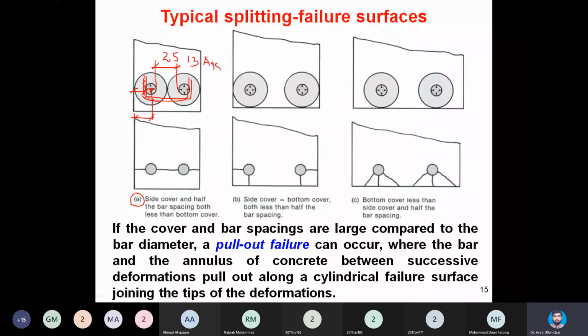If for example we have 19 millimeter, the coarsest size of the particle, then we will end up with about 25 millimeter if the dia of the bar is also 25. So more or less, if bar dia is 25, the recommended clear gap between the bars is again around 25 millimeter. Now imagine that while placing the steel in the formwork, you compromised on the edge cover, and you also compromised on the clear gap between the bars.